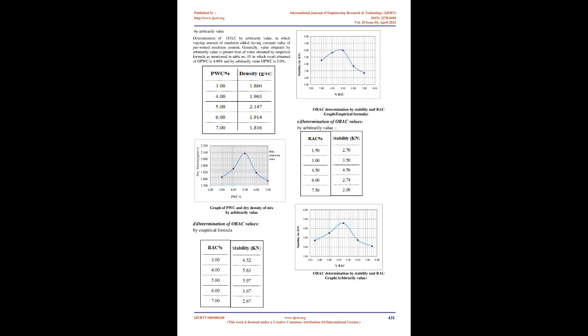E. Soak stability test and variation of residual asphalt content, RAC. By maintaining a constant OTLC value, the RAC is varied in a range of 7 to 10% emulsion content, EC, with 0.5% increment in RAC. Specimens are mixed and compacted at each of these RAC values. Then the same curing process is followed up to the completion of oven curing, as explained above in the case of the dry stability test. The dry samples are then water conditioned, by capillary soaking.